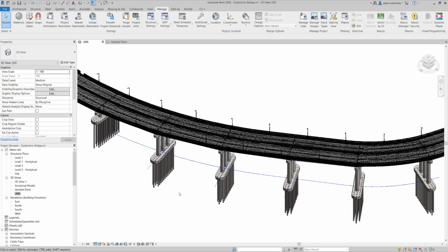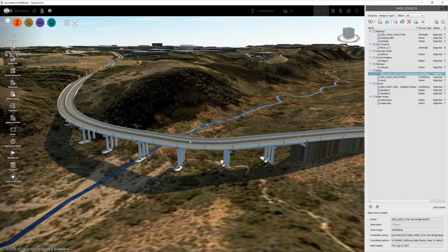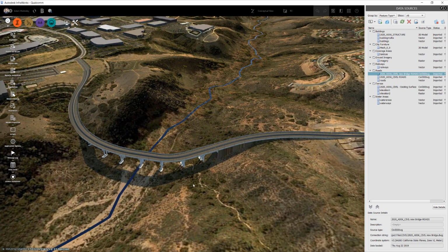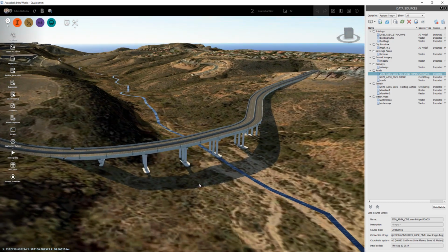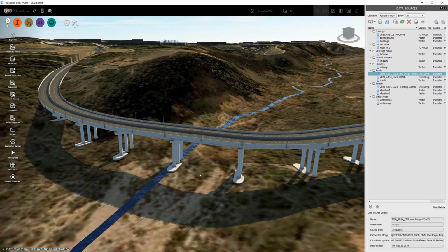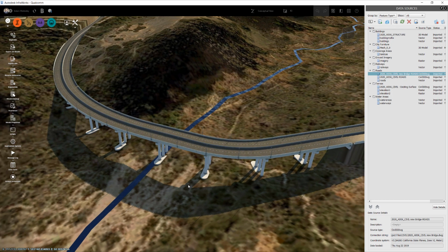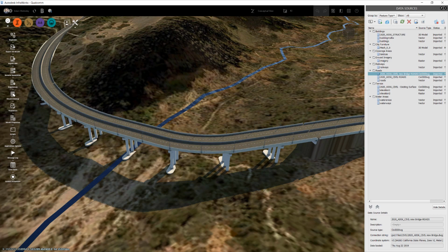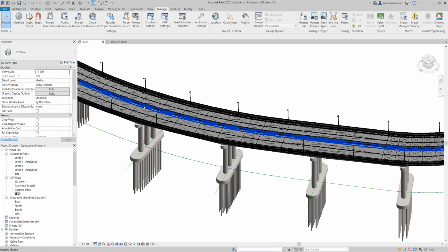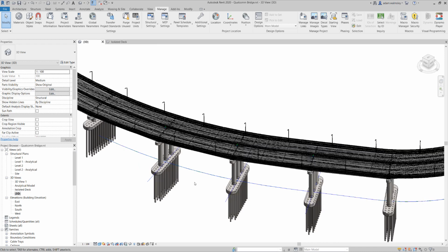So I suppose in summary today, I've shown you how you can start off with a really simple road design by a planner or someone else in the design team. Bring that information into Civil3D, really refine that alignment to the proper standards, and then assign vertical profiles to that alignment. Bring that information back into Infraworks, where we can really quickly start to sketch a bridge and get something pretty nice with correct span lengths, and girder lengths, and spacing between the girders, and all that kind of information. And then send that out to Revit, which, as I said, took about 5 minutes to get that Revit model. And then from here, you can start to really look at putting your drawings together quickly using sections and elevations and plans. And then, as I've shown you with Dynamo, the ability to just extract some data out of the model, which is useful on documentation.